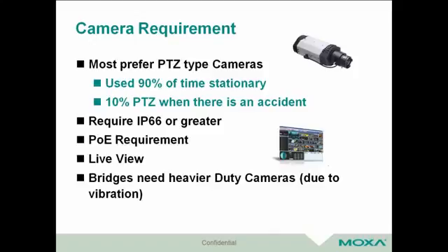That's where you're put in a gray area where you really want to focus on, okay, if I want to put on a camera, will I go with something that's not a standard, or can I live with that and probably migrate into something later? But keep that in mind when you're dealing with PoE and cameras, because for the high-end power PoE there's no standard yet. The standard PoE, the 30 watt, 802.3at and af, is more or less where the lower end power is, and that's pretty much basic for most cameras out there.